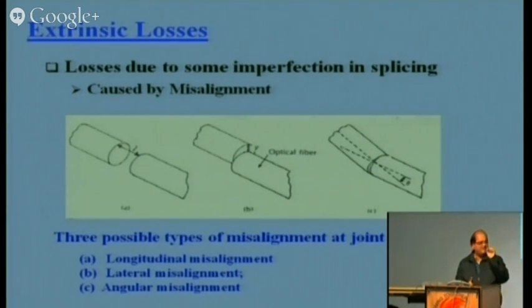1 micron is a very, very small measure. Simple calculation, it is the area of mismatch. You have a 10 micron fiber. If you calculate the area, pi r square, so r square is 100. But if you are offset by 1 micron, 10 micron will be left with 8 micron. 8 square is 64. So 36% loss will be there. So it is a precision at micron level.